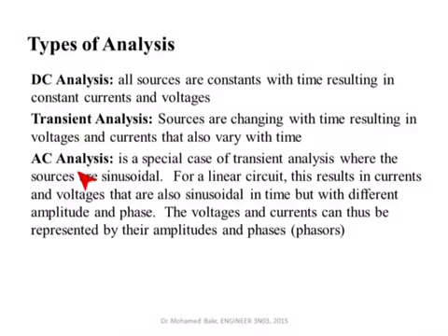The last type of analysis, which is the one relevant to phasors, is really the AC analysis. AC analysis means that you have sinusoidal excitation. So the voltages and currents are all sinusoidal. Usually for a linear circuit, this means that you have a source which is sinusoidal, and all the currents and voltages in the circuit as a result will also become sinusoidal with the same frequency. They will differ only in amplitude and phase. So these will be the only two different things. So in that way, all voltages and currents can be represented by phasors.